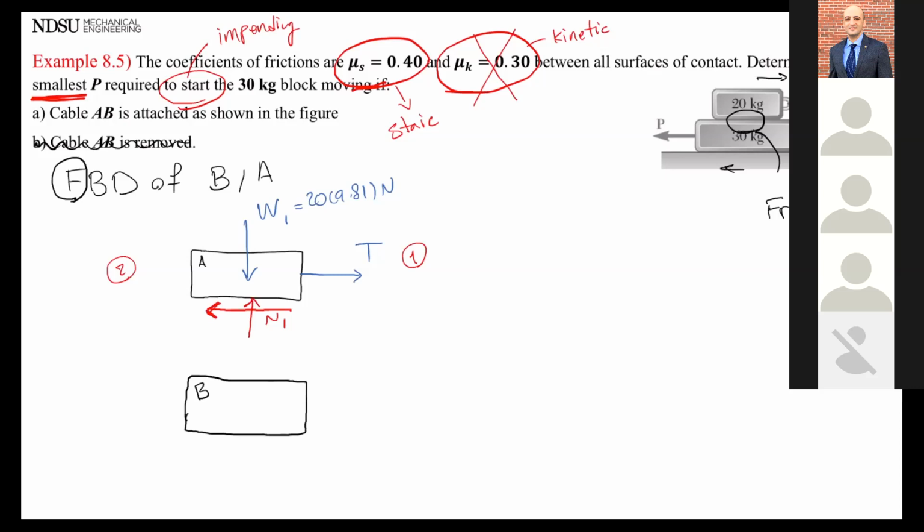Block A is going to move to the right. The friction needs to be opposite and going to number 2. Okay, but if you have doubt about this, you can leave it and do the more obvious one, because block B is more obvious. It's literally going to move to the left, and we can figure that out. But I think everyone is having a good understanding here. Let's move on to block B.